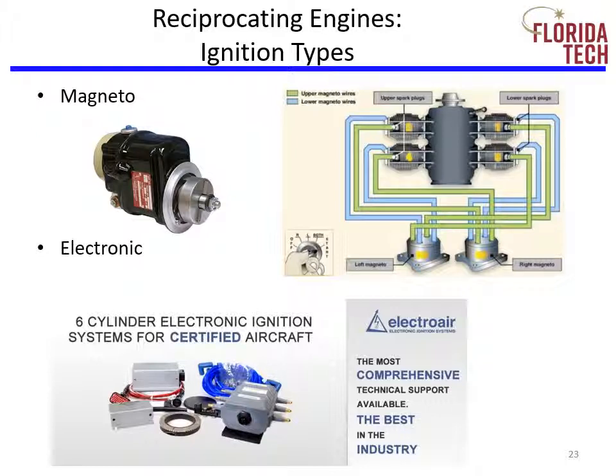That means if the airplane's electrical system were to fail, the magnetos would still be able to generate sparks for the engine to run. The energy generated from the magnetos is sent to the spark plugs. Spark plugs then release that energy, which ignites the fuel-air mixture, creating power to turn the propeller. Most airplanes have 2 magnetos, multiple sets of wires, and 2 spark plugs per cylinder in order to increase efficiency and reliability of the system.